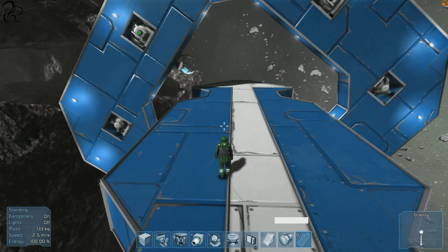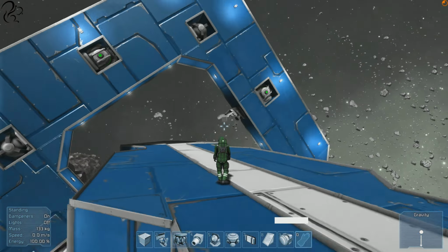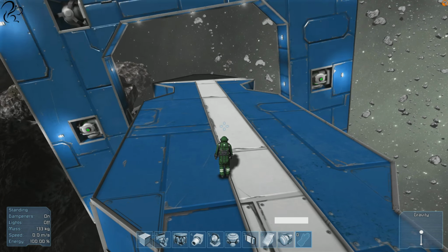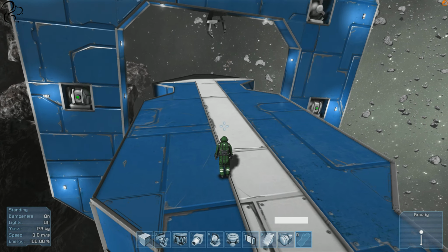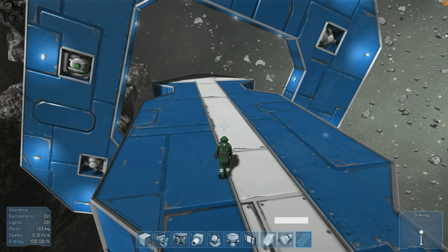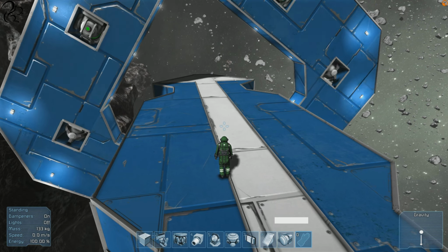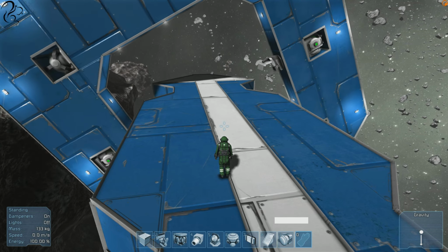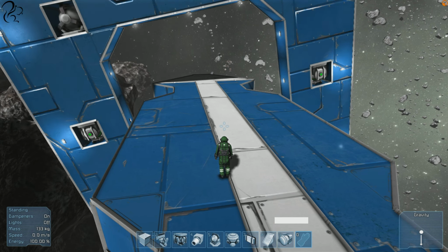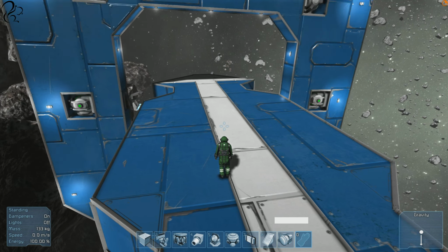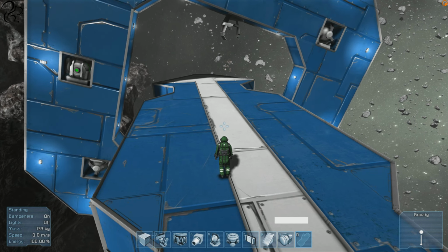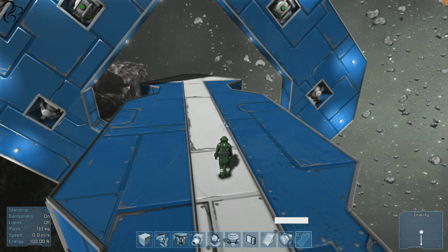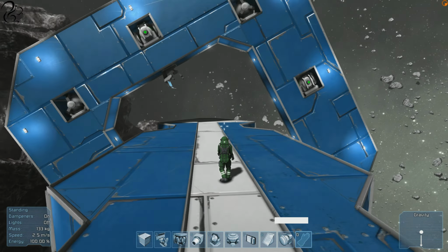We learnt about gyroscopes. Now gyroscopes, as we know, will stop rotation of the current craft. They stop the rotation in any direction. They're able to do that. In order to stop translation, which is movement in any of the X, Y, and Z directions, you need to have thrusters. It will use the thrusters to, if you like, apply an opposing force to the direction in order to bring the object to a halt. If you don't have thrusters pointing in all 6 directions, then it won't be able to do its job properly.